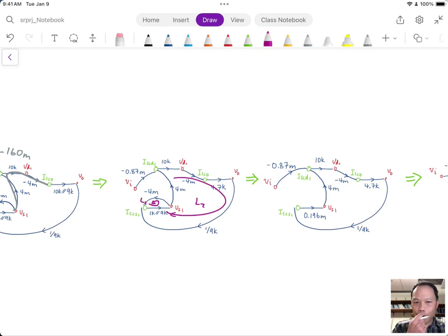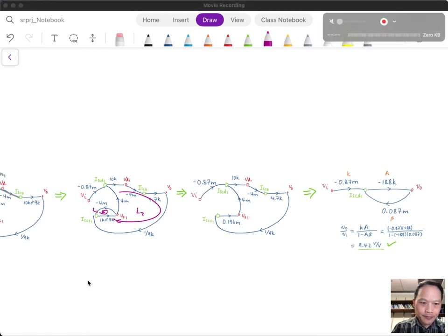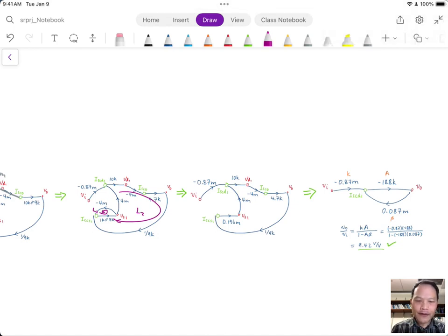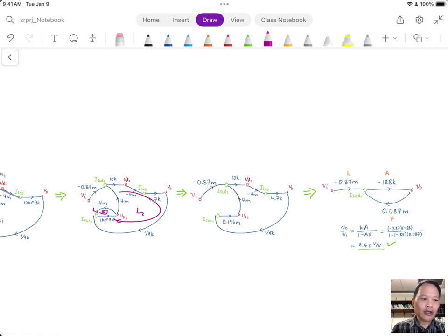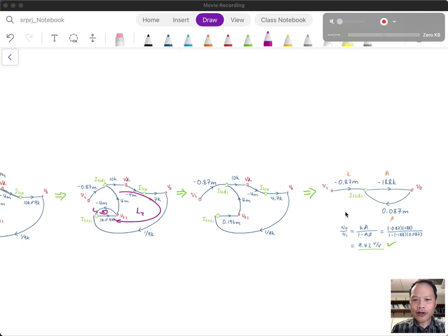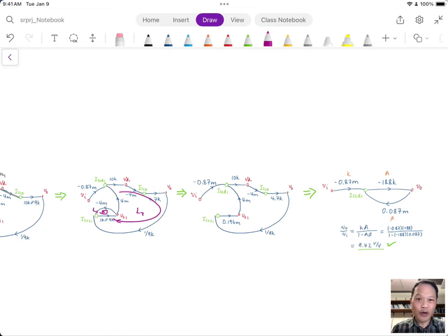And you can see how we can simplify the signal flow graph through operations, and this is fundamentally different than the modifications of the original circuit in the traditional approach, because here the modifications are done on the signal flow graph. The signal flow graph is basically a visual algebra, and simplifying it is akin to algebra: eliminating variables and dropping non-dominant terms. So we are not modifying the circuit, we're simply manipulating the equations in effect. And this gives us a lot more confidence in modifying the signal flow graph in order to get an answer.